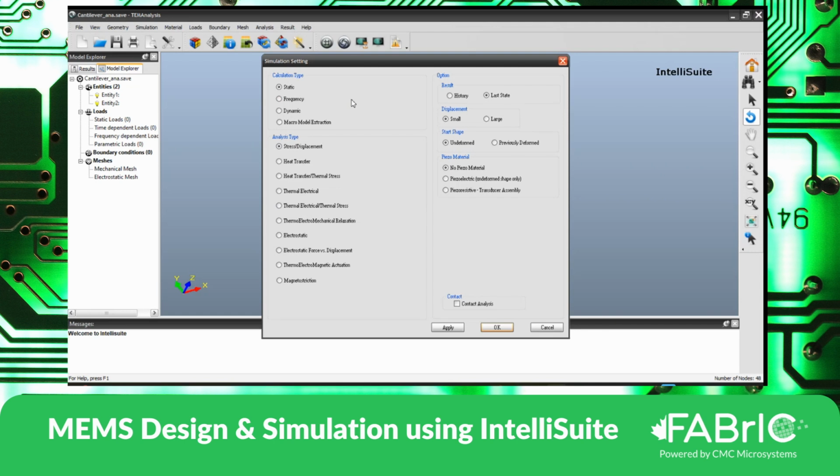In simulation settings, what do we see? The calculation type. What do you want to do now? You want to perform a static simulation or a frequency or a dynamic based on your preference. Another preference is what is the physics behind it. So you want to perform a stress displacement where, for example, I apply a pressure and see the deformation, that's stress displacement.